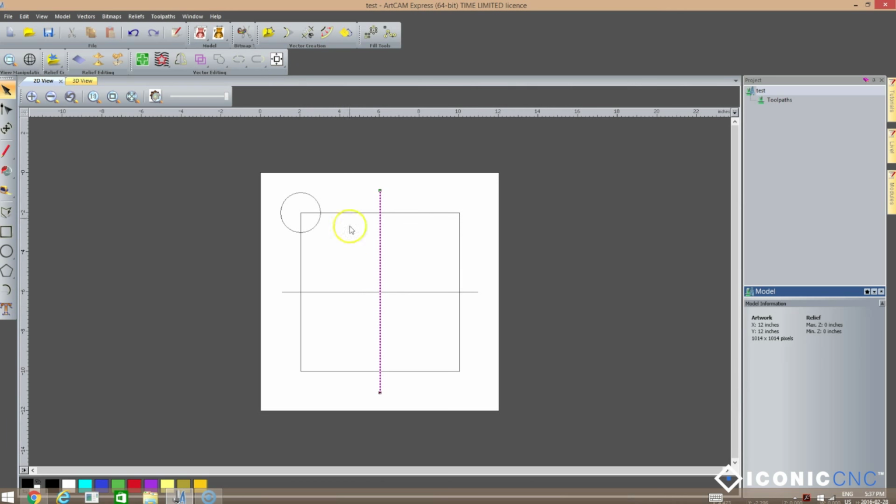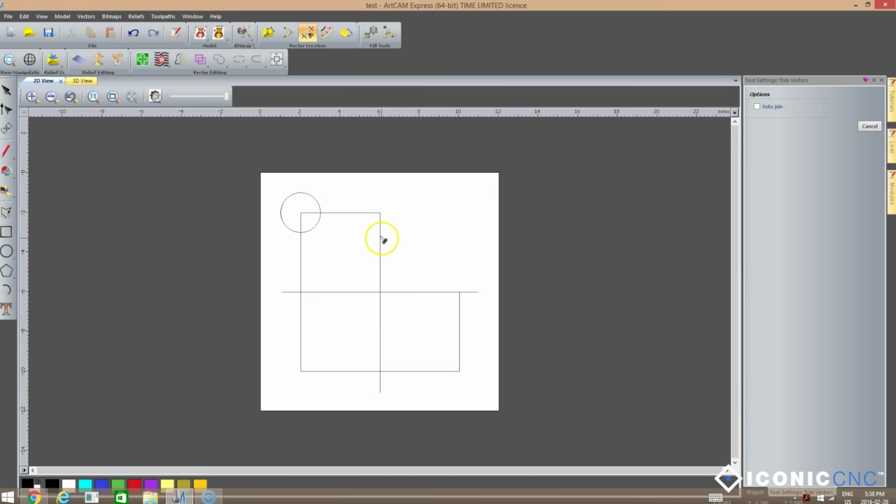The next tool that we're going to use is up here. It's called the Trim Vector tool. And exactly as you might think it would, if I click on it, it's going to trim off whatever pieces of this object that I've created that I don't want. Now you'll notice as I move my cursor onto the workspace, my cursor has magically transformed into a pair of scissors. I want you to watch what happens as I move the scissors over a line. You'll see how they open, and if I left click, it trims off the line wherever. It basically trims off the line between two intersecting points.